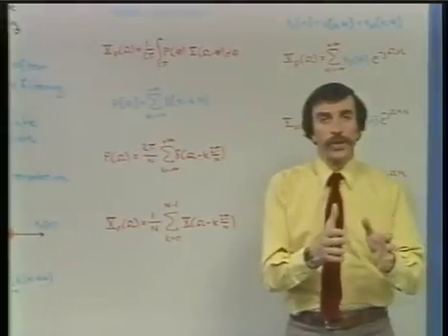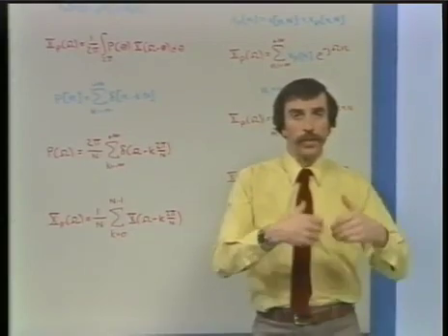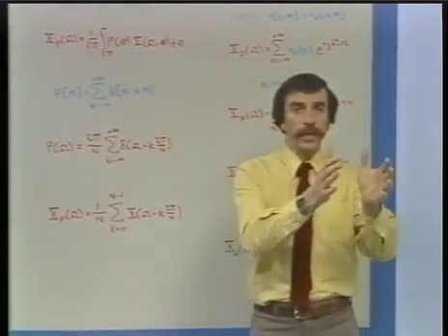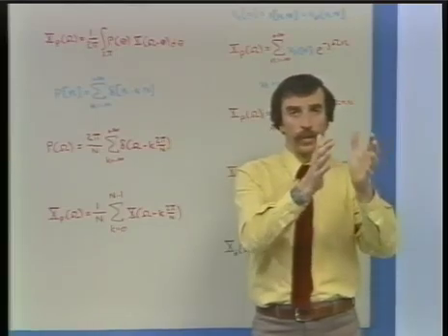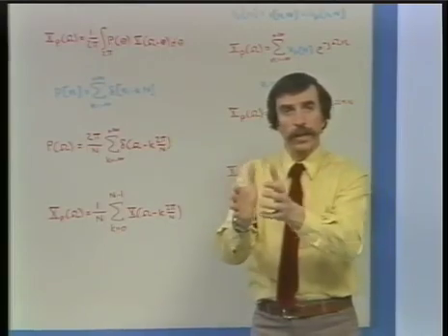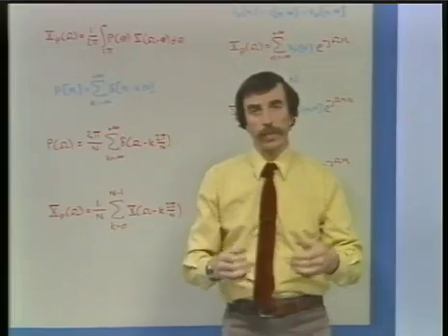In other words, what we're doing, very much as we did in continuous time, is through the sampling process, when we look at it in the frequency domain, taking the spectrum of the sequence that we're sampling and shifting it and then adding it in, shifting it by integer multiples of the sampling frequency.